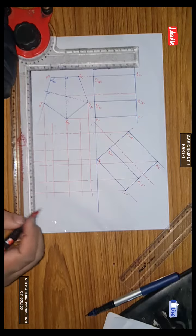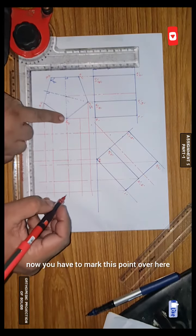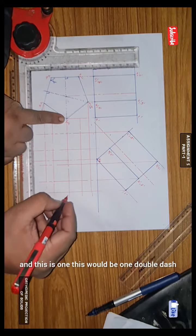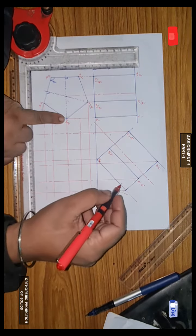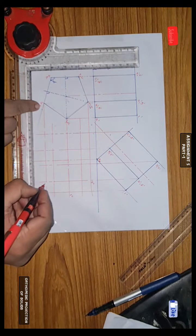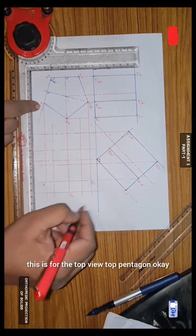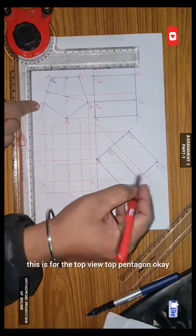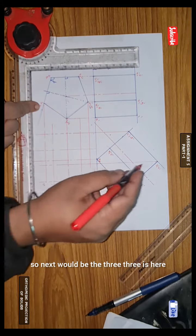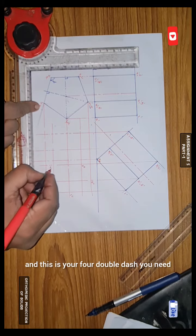This point would be 1 dash, this would be 2 dash comma 5 dash, this is 3 dash comma 4 dash. Now you have to mark this point over here, like this is 1 and this is 1, this would be 1 double dash, and in this position this would be 2 double dash, this would be 5 in this position here, 5 double dash. This is for the top view, top pentagon. Okay, so next would be the 3 is here, 3 double dash, and this is your 4 double dash.